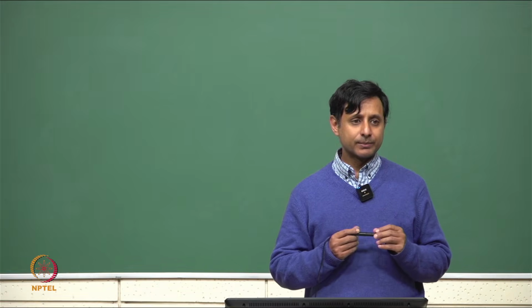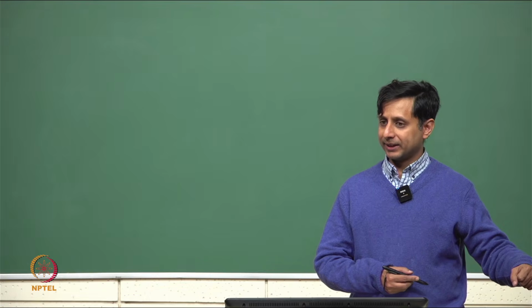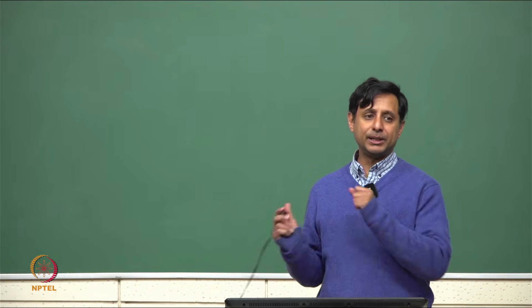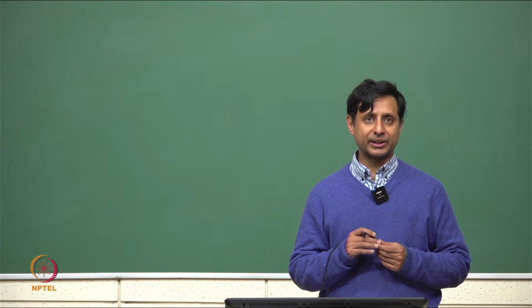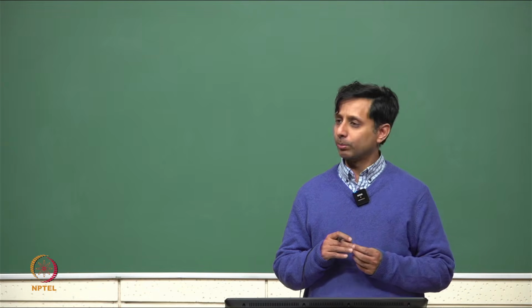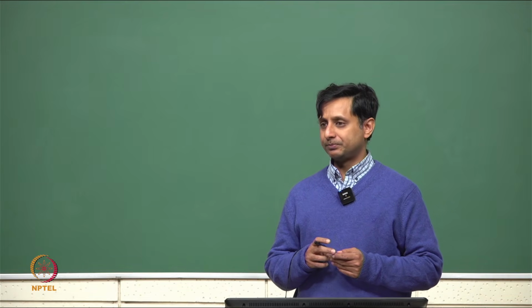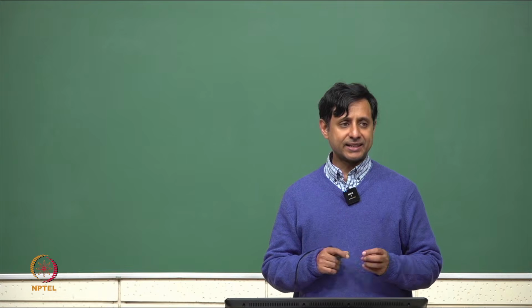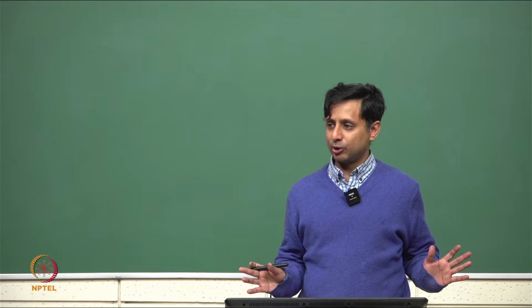I bring it home. First, I apply voltage V1 at port 1 and I take an ammeter and measure the current in port 2. Basically, short circuit current in port 2 is what you are measuring and you call that I2. Next, you dismantle the ammeter and voltage source.